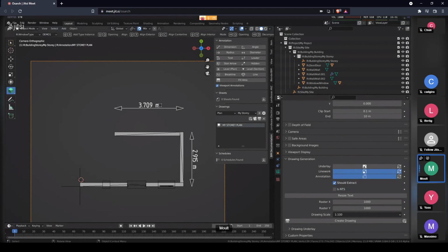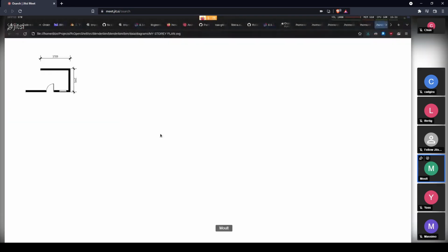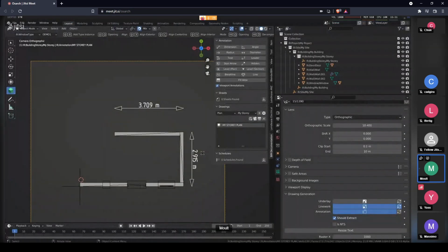And then I would go and move around the annotations, because that's typically the workflow. You'd spend a lot of time just shuffling around annotating things, and you don't need to recut your entire drawing every single time. It's a waste of time. And if you enable that little cache, well, you can almost not tell because it's such a tiny model, but it's basically instant to get the results. So it's a good thing to do.